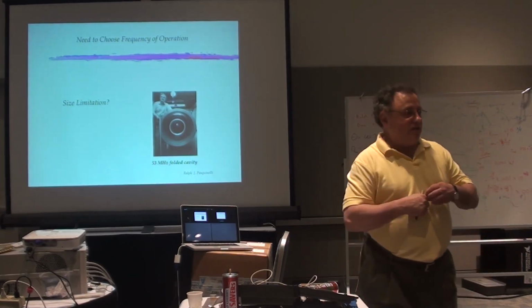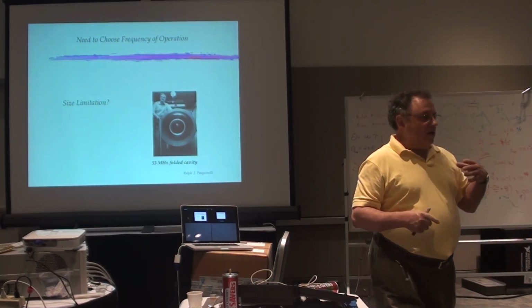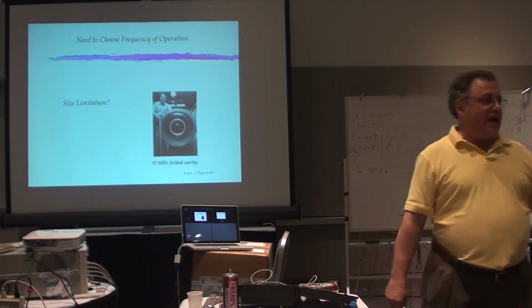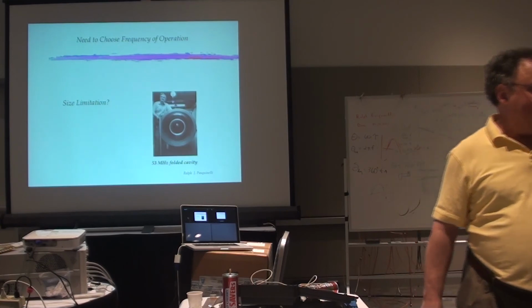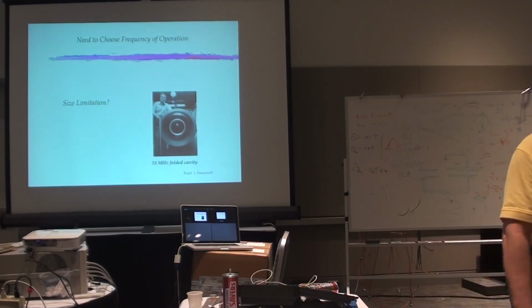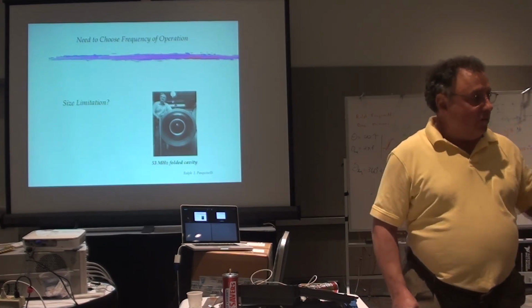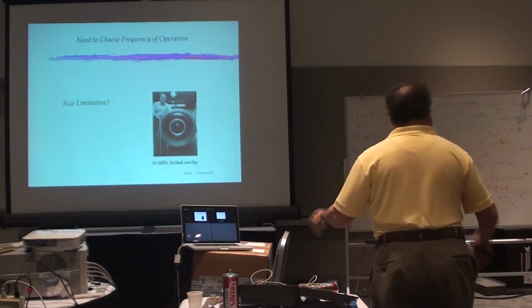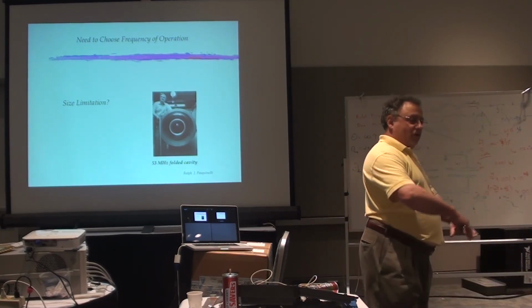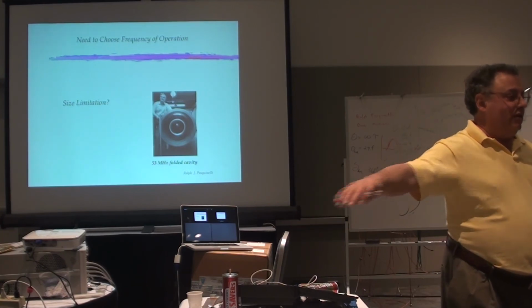They used triodes and tetrodes, which down at 53 megahertz, certainly when Fermilab was designed, was the way of doing things. There was certainly no solid state to help you there, and it's way too low in frequency to have klystrons or magnetrons. And 53 megahertz is kind of a nice number because we did want to have a lot of bunches, and the machine was going to go around for 4 miles, and at 53 megahertz I could put 1,113 bunches in the machine.